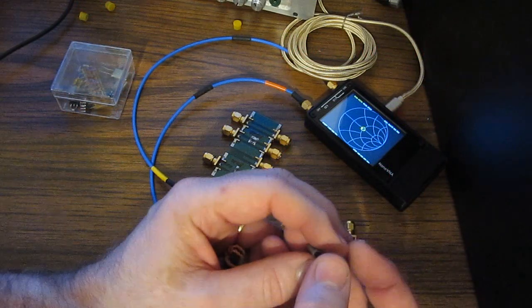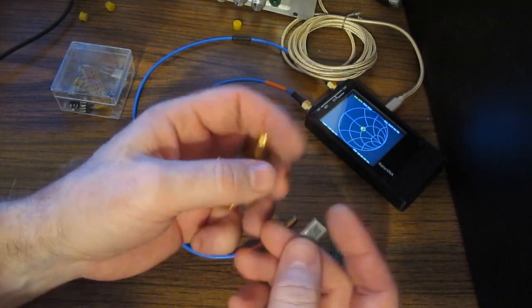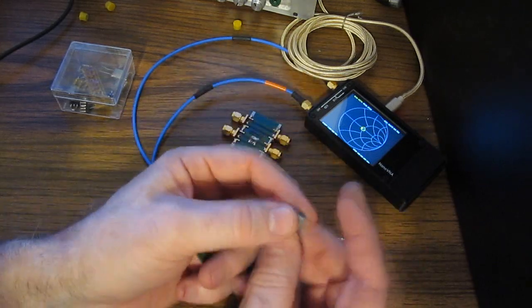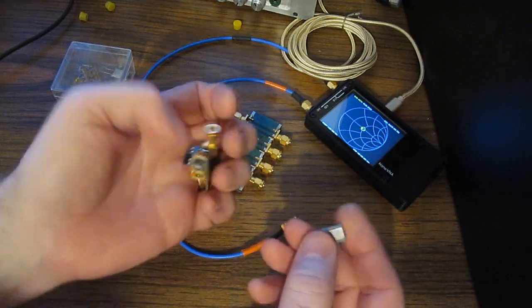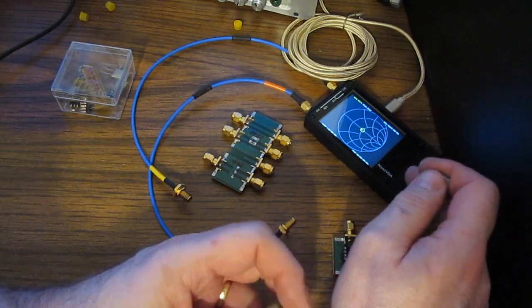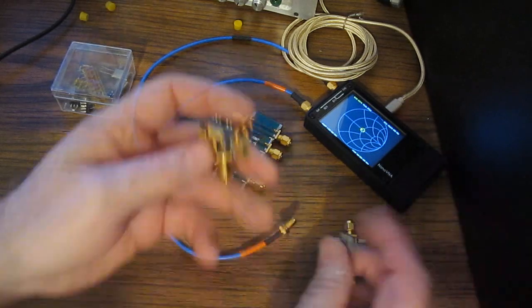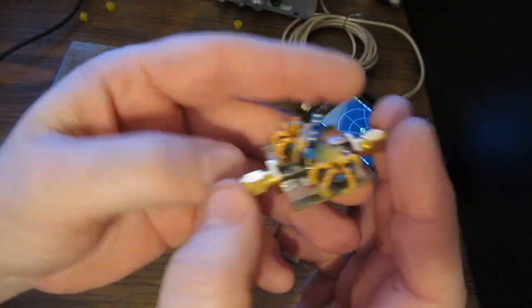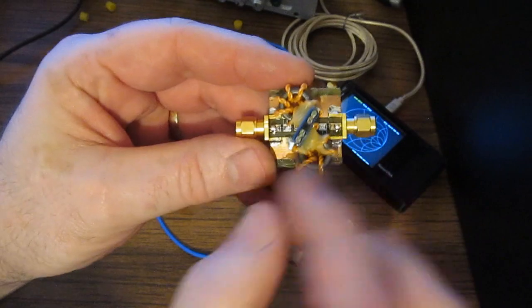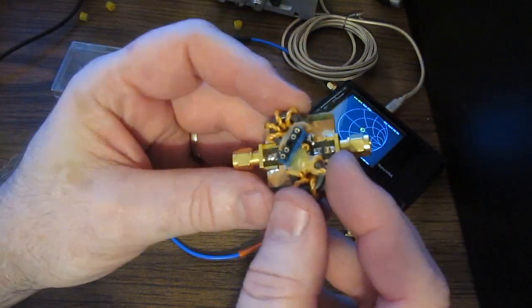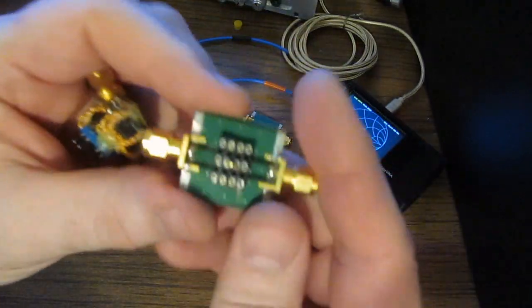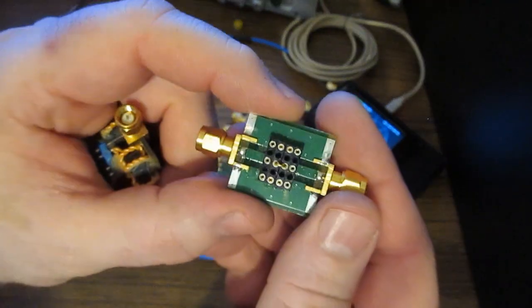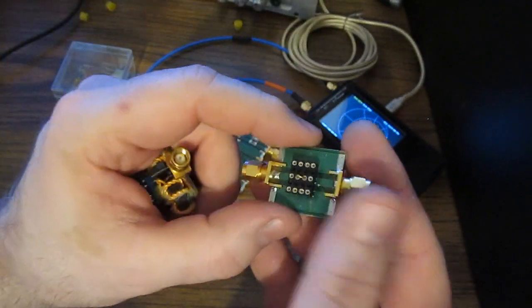When I made the review for the NanoVNA Plus, I mentioned that it couldn't be used for narrowband measurements. And again, that was the whole reason that I released the software for the original NanoVNA, because this unit is capable of making those measurements. So here again, we have our small fixture. This is nothing more than two 3dB attenuators and then two transformers. Again, this is here just for impedance matching. Again, if you're going to try to use a fixture like this, it's probably not going to work very well.